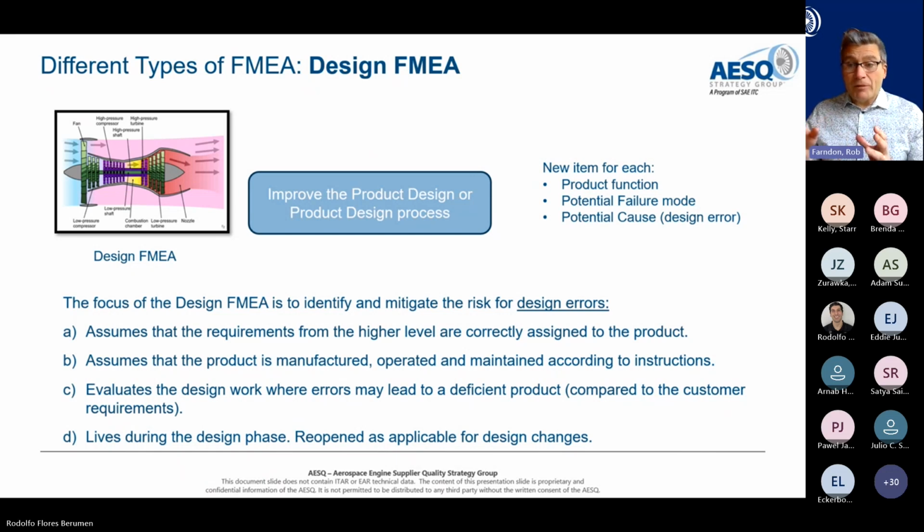But you can reopen it, and it's appropriate to reopen the DFMEA when something changes. So if the operating environment changes, or the requirement into us as a design organization changes, that is a perfectly good reason to reopen a DFMEA and again reevaluate whether or not that design might satisfy the requirements. But it is intrinsic to design.